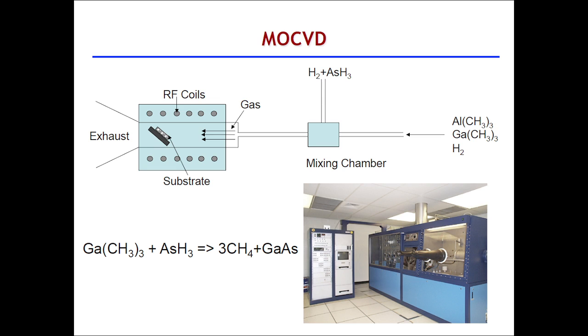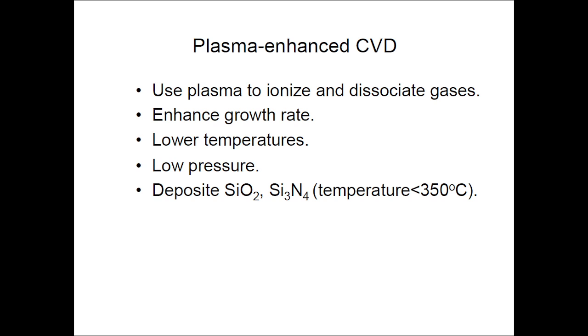So this is a technique of MOCVD, metal organic chemical vapor deposition. Here we'll be using an RF coil, and we'll have a precursor over here and the substrate over here. So we will have a mixture of elements over here. These elements will be mixing in this chamber, and the vapor coming out of this mixture will be collected over this substrate by applying a voltage across it, and that's how the chemical vapor deposition works here.